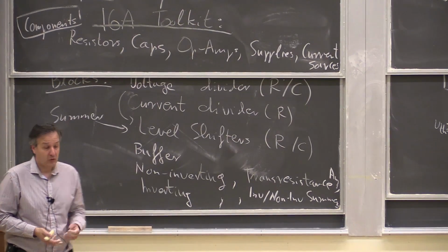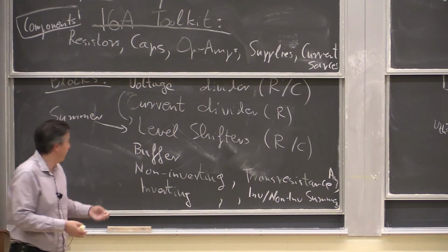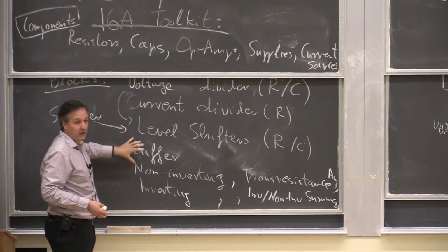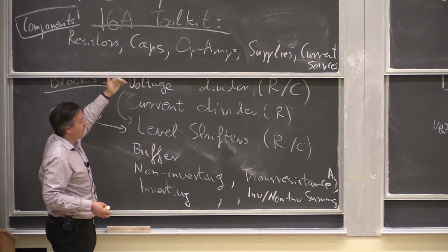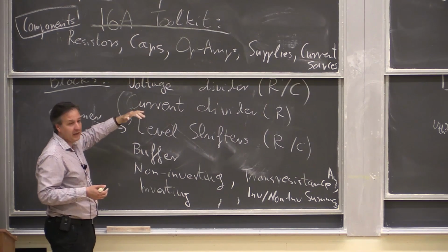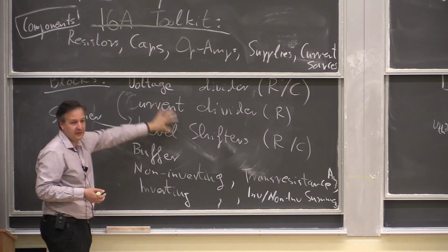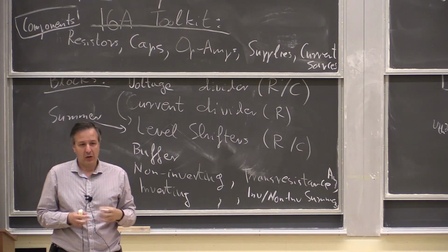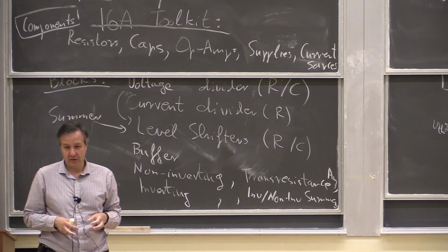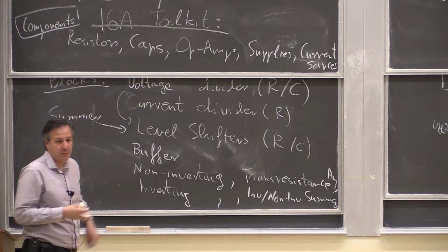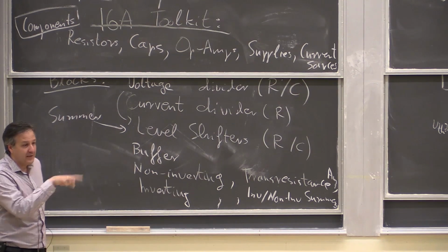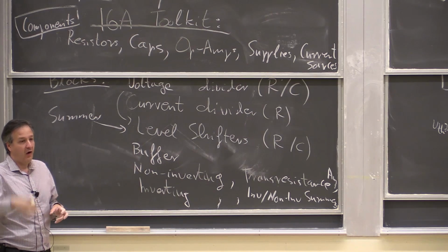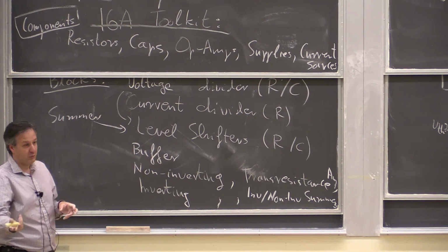Right? So try to practice these kinds of things because when you're thinking about the strategy, you want to know the physical principles. When you're thinking about implementation, you want to have these blocks ready in your mind just like Lego blocks. How could you quickly put something together? You could say, oh, this looks like a sum. Okay, I'm going to use some sort of a summer. The next thing, oh, I need an opposite sign, so I'm going to use some sort of an inversion.